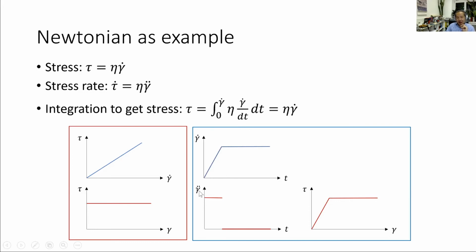You see here, I just put here the acceleration over the time, right? And when you start, you got the acceleration, and I can make use of the model to give a stress increment. Afterwards, the acceleration will be zero. You get this stress strain relationship very much like here. Compare left to the right. So it is very important to have this acceleration stage. But what happens if the shearing comes to a standstill? You stop it. You cannot stop it just now. You need to decelerate until speed is zero. And later we will have a look at this whole thing. It really brings something very, very interesting. You get a quite different perspective on this.